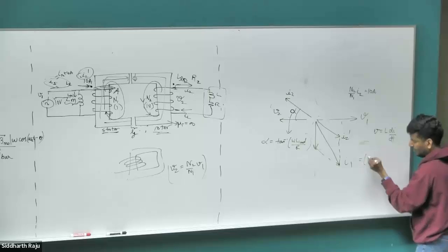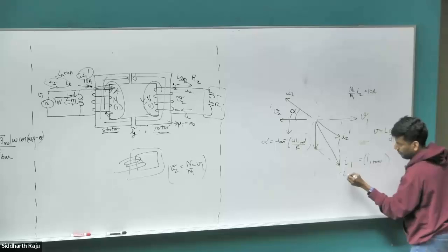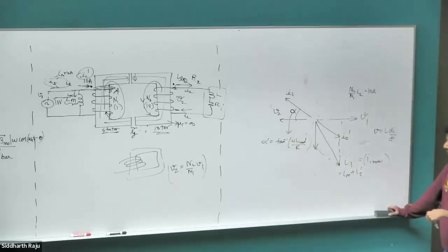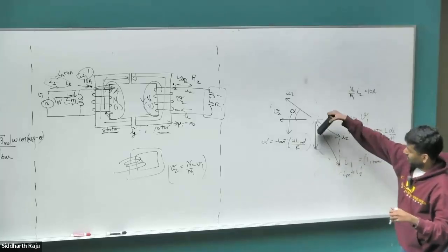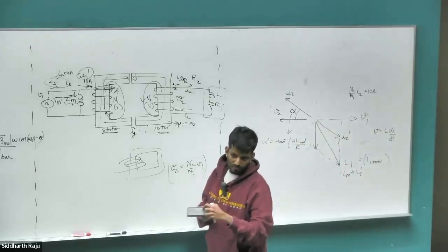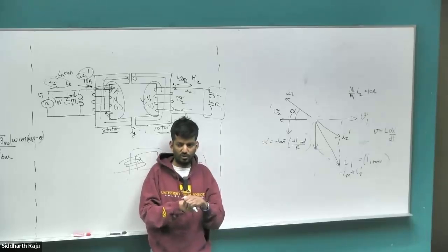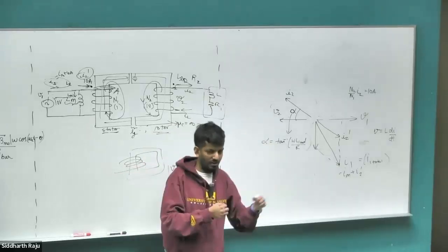I1. Previously we were calling it I1 total. Equal to the magnetizing current plus the current flowing on the rotor, the reflected current. Right, so this is where the problem again is. What is the disadvantage of having a very large IM? Why do we want to minimize the IM as much as possible? What is the objective of reducing the area of an induction motor? Why not just have a high IM current?